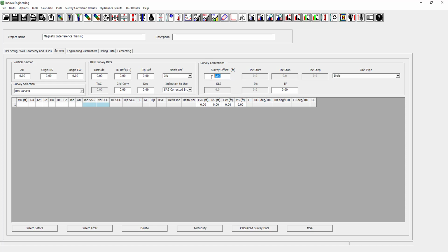So I will now enter in the data that I've got for this example. And don't forget to change your grid reference to true if your surveys are referenced to true north. So now that I've entered this information, I can start entering my surveys.